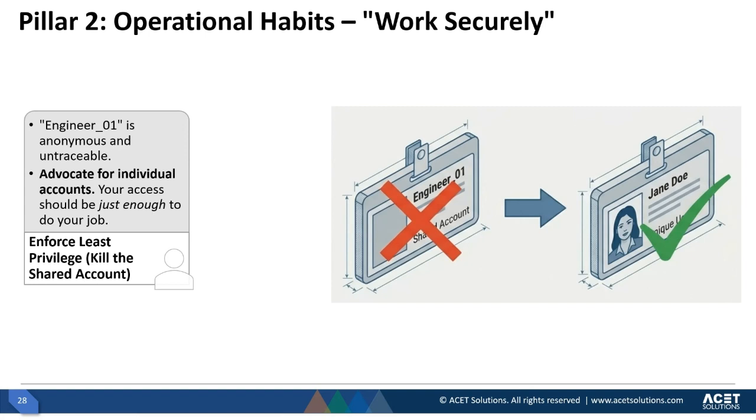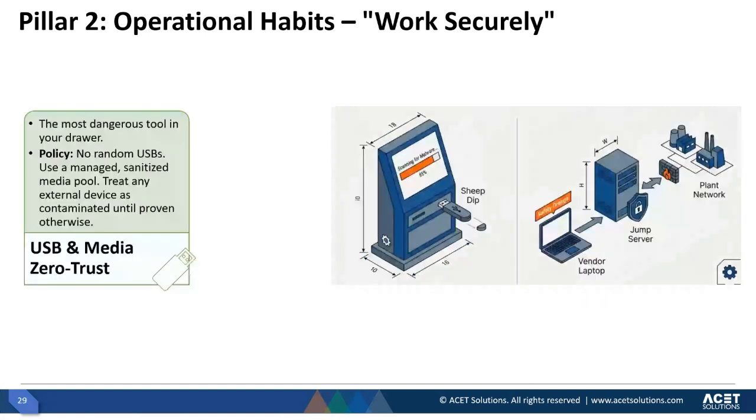In the operational habits, obviously there are multiple things, and using USBs or remote access is also one of them. Do not use random USBs on the control system, even on your personal laptops or personal computers. It's better to sanitize them before using anywhere, and especially for untrusted sources, never connect USBs to the control system network.